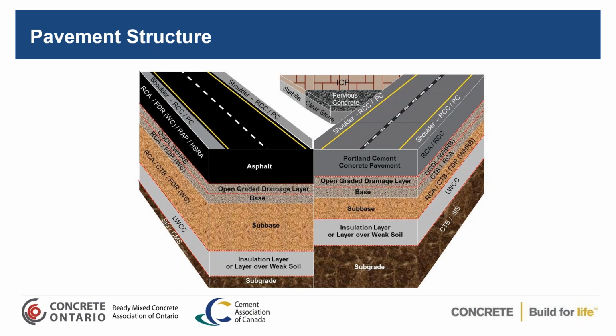I'm not a real big fan of them, but if you have them, there's a couple of things you want to make sure you consider. It's going to change the effective thickness of your pavement, because a small amount of the paste and the fines will penetrate down into the open graded drainage layer, because it is around a 25% void ratio. So when you do your joint cutting, you may end up having to cut a little bit deeper, maybe 10 millimeters more. Because of that, you have to make sure that you're very careful not to hit your dowel baskets. That would be one thing.